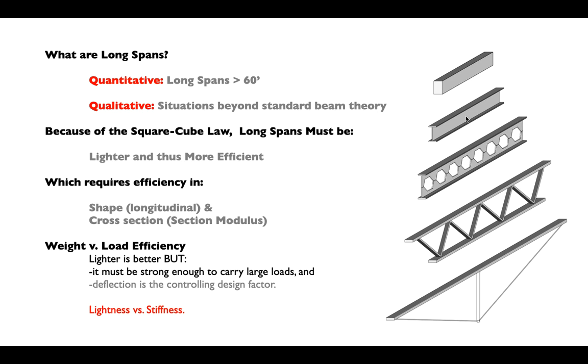Now, a very, very simple long span technique would be to take that I-beam and to castellate it, to cut a zigzag line through it, to take the resulting two pieces, shift them by one phase, and get basically a kind of supercharged I-beam, where the flanges are further apart, right, because we've expanded the beam basically. We've taken weight away from the neutral axis. Note that those open hexagons that come from that zigzag cut are basically removing weight from around the neutral axis, the center of the beam where it's least effective.